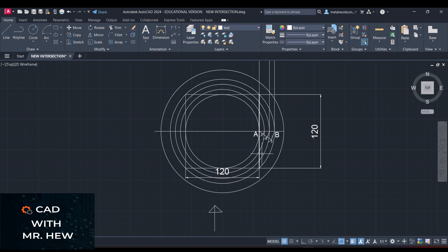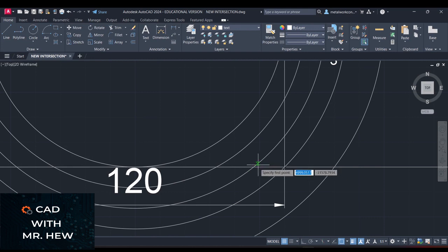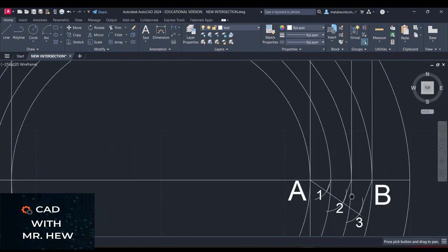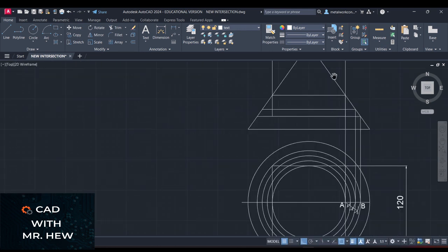So where the second disc, this one, intersects this line, you're going to project a line going up. Okay? So we go here at the intersection, which is right here. Can you see? Right here. Good. We're going to draw a vertical construction line to intersect the disc in the front elevation. All right. So look now. Its disc is here. Isn't that so? Yes. There. Enter.